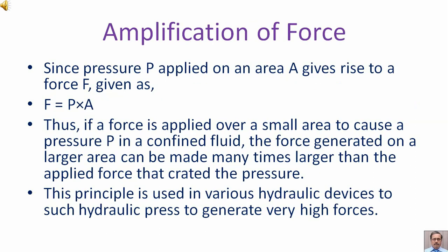Amplification of force. Since pressure P applied on an area A gives rise to a force F, given as F equal to P multiplied by A. Thus, if force is applied over a small area to cause a pressure P in a confined fluid, the force generated on a larger area can be made many times larger than the applied force that created the pressure.